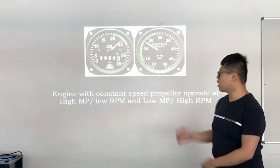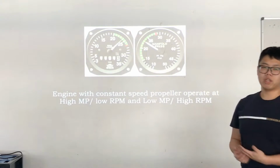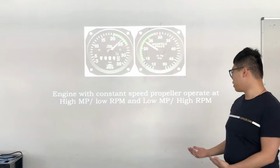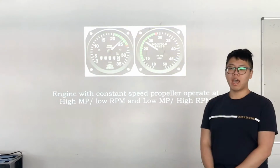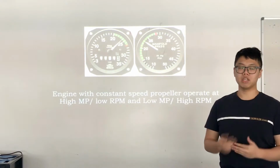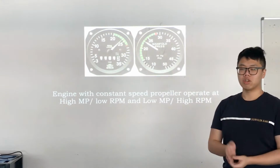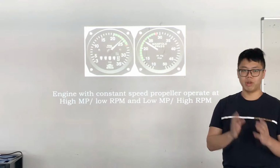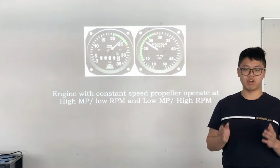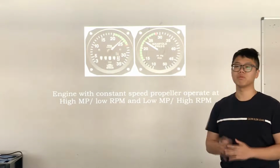In my part, I'm talking about engines with a constant speed propeller. They operate at a high manifold pressure and low RPM, or a low manifold pressure and high RPM. With a constant speed propeller, the pilot can adjust the propeller's RPM and the manifold pressure. So if the pilot sets the correct manifold pressure and RPM, they will have good efficiency for the fuel flow.